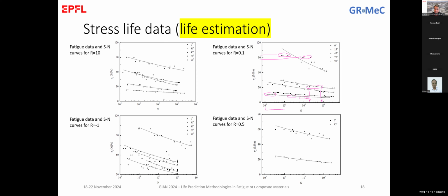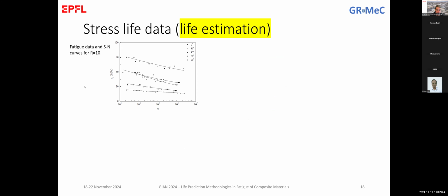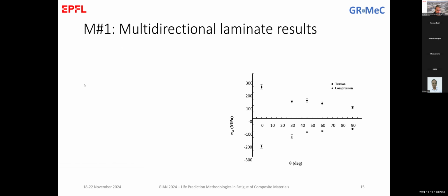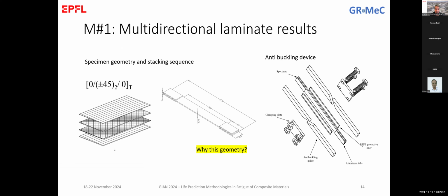No, the reason I am asking is because in the fiber dominant properties, the effect of cutting at a slightly wrong angle, like not maybe perpendicular, and all those effects will be predominant. Yes. Rather than 60 degree and 45 degree. Yes, I agree with you, but do not forget, and this is a point that we discussed yesterday, do not forget, I'm going back, the laminate that we have here, and my 0 is not an actual UD.